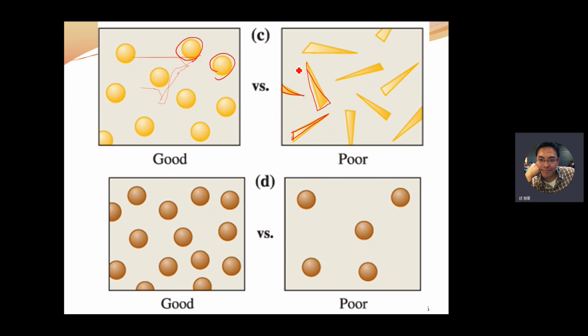Because if this alloy is withstanding some applied stress and its dispersed phase is needle-like, it is easy to trigger dislocation, slip, or cracks, because we have a sharp tip right here.